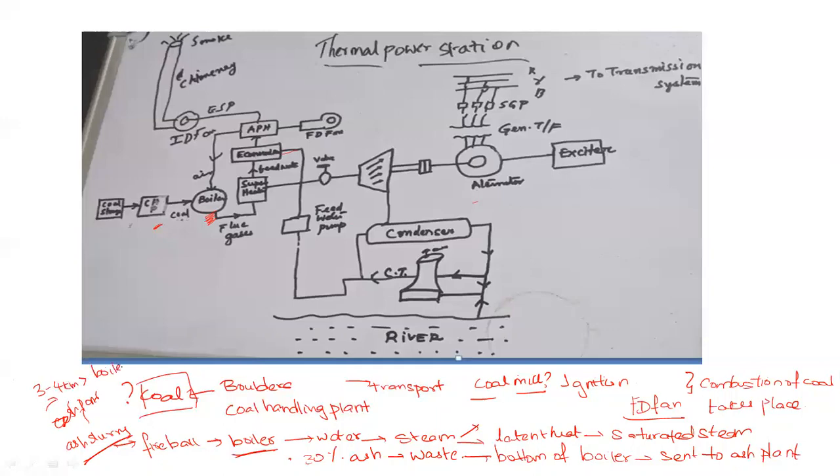This ash pond can accommodate the ash slurry for 25 years. Such a big quantity of ash slurry is transported daily and collected in the ash pond. The pond is a huge structure, a valley-like thing, and the ash slurry stays there. So please think about how much coal is required. For a 250 megawatt boiler, coal required is 100 tons per hour, or 2500 tons per 24 hours.